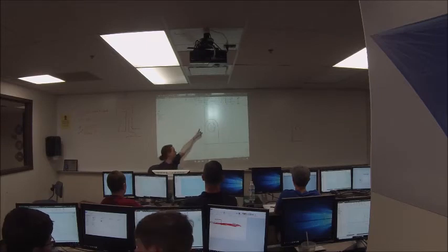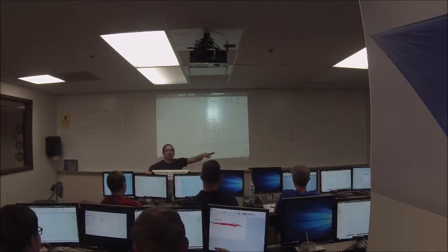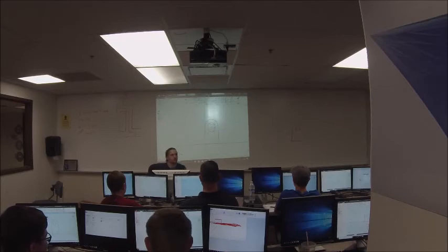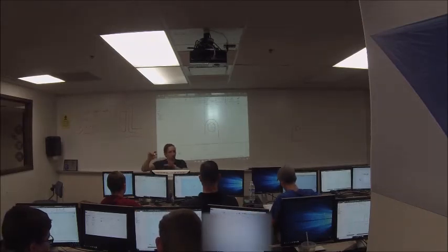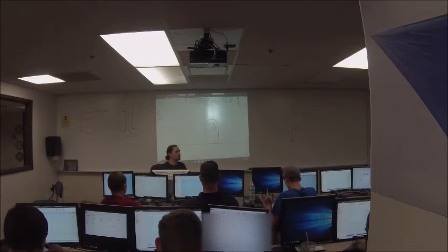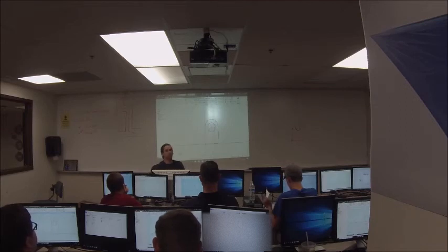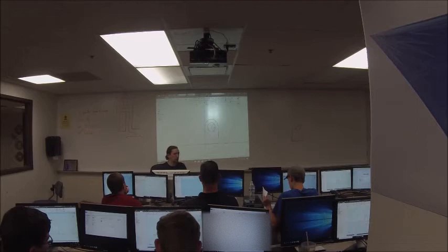Now you'll notice all your dimensions, all your constraints, everything stays, but it just neatly cuts off geometry that you don't want. That's useful in a lot of cases because sometimes you'll end up with a lot of extra geometry. You want to trim it out. Just be aware if you trim too much, you'll end up removing some constraints, and you'll have to go back in and add some constraints to get your geometry to fully constrain again. But that's the trim tool.